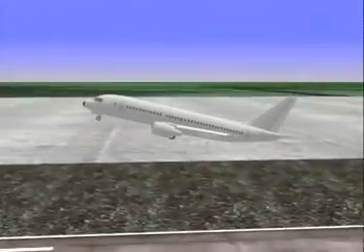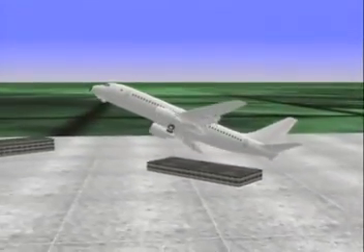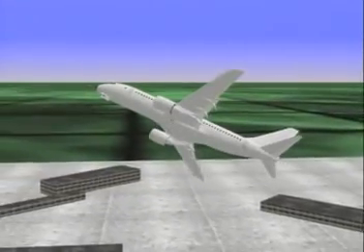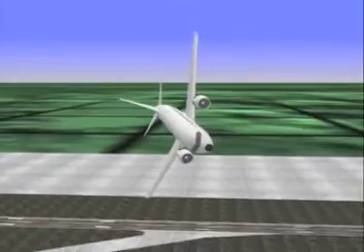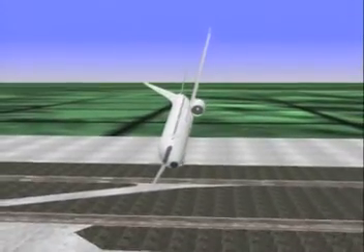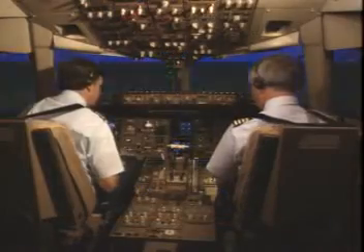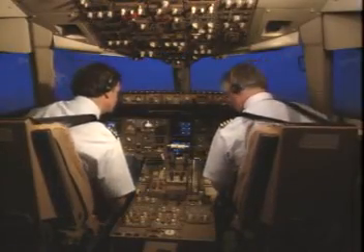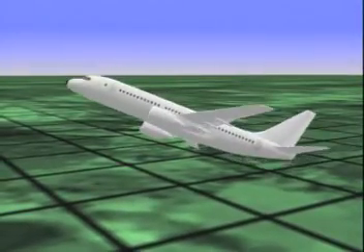Airplane upsets do happen, but they are rare. Because of this rarity, a flight crew that finds itself in an upset situation can quickly be overwhelmed. Causes of upsets vary. They may be caused by environmental factors, by component or equipment malfunction, by human factors, or by a combination of any of these. But no matter the cause, the foundation for recovery is the same.